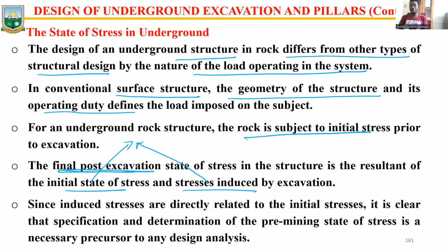These together will give you the final or the post-excavation stresses. Since induced stresses are directly related to the initial stresses, it is clear that specification and determination of the pre-mining stress is a necessary precursor to the design analysis.